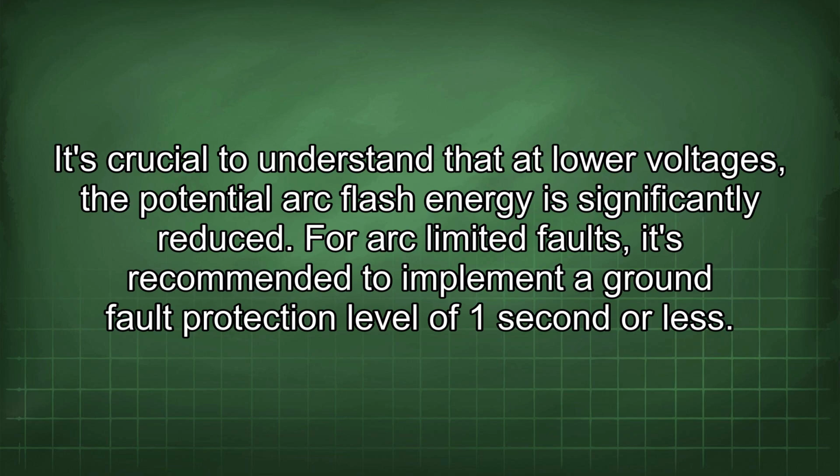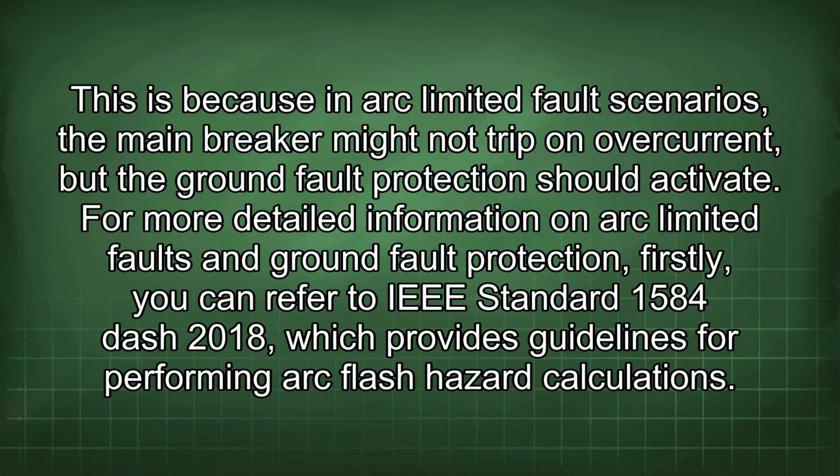For arc-limited faults, it's recommended to implement a ground fault protection level of 1 second or less. This is because in arc-limited fault scenarios, the main breaker might not trip on overcurrent, but the ground fault protection should activate.